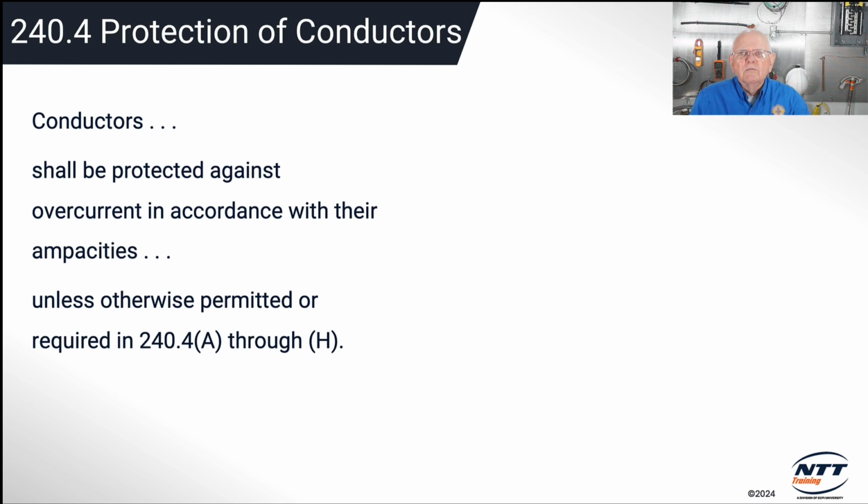Minimum resistance, maximum current flow. So the upstream breaker back in my panel board is going to trip as quickly as it can. We're going to say it's going to trip instantaneously because of that large amount of current that flows. Instantaneously, look that definition up as well. It just simply means no intentional time delay. So it's very quick, I'm sure in a matter of milliseconds on a molded case breaker, depending on what you're using. But anyway, it'll be extremely fast, and that short circuit will trip the breaker. Now, very similar is a ground fault.